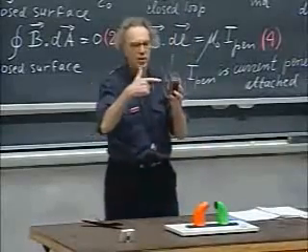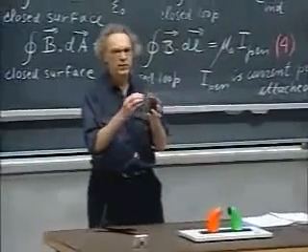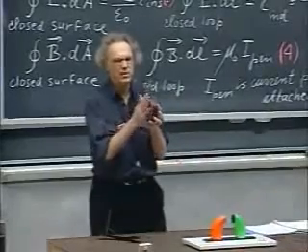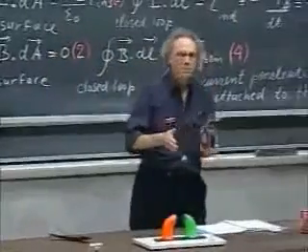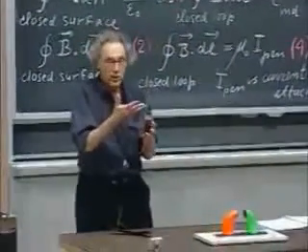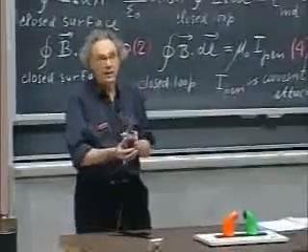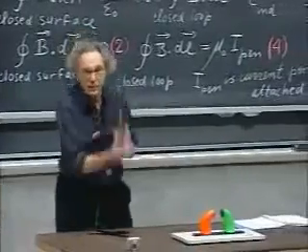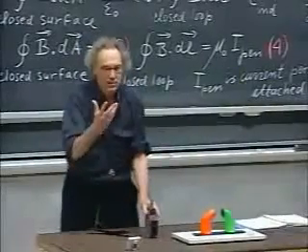And when I move this between these poles, magnetic field, let's say, is going in this direction. I don't know whether it's in this or that. I don't know the color code. But there is a magnetic field going through here. So there's a change in the magnetic flux through this surface. Very crazy surface. If there are 1,000 wires, this surface goes 1,000 times like this, remember? And then there is going to be an induced EMF. And there's going to be an induced current. And this light will glow a little. If I go in very slowly, you'll just see a teeny weeny little light. If I go very fast, then the magnetic flux change is high. High EMF, a lot of light.